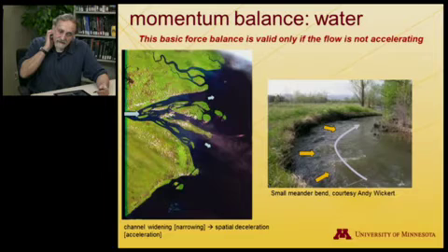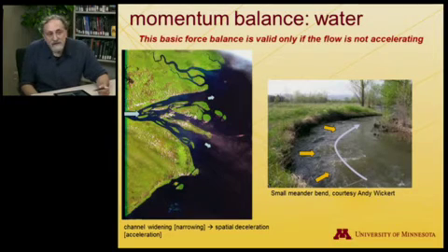Now, there is a caveat to this. Normally you don't get something quite this easy in science for free, and in this case, the price is that we have to make some fairly severe assumptions here. And the main one is that since we assumed steady state, and since we assumed that there was a balance between only two forces, basically the two most basic forces acting on the fluid, it's important to realize that that implies that there can't be any other accelerations or any other forces acting on the fluid.